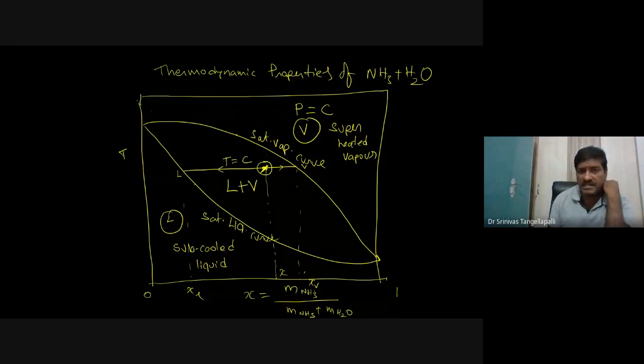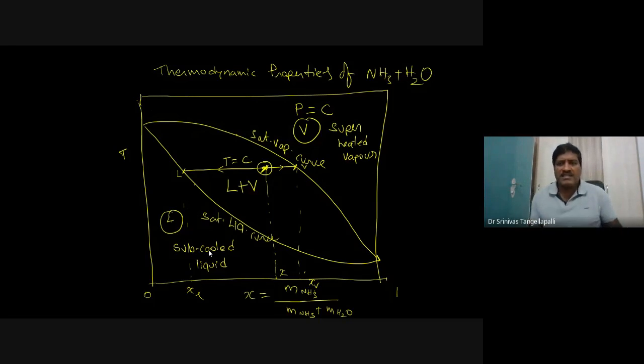One is the concentration directly at that state, that is the strong solution concentration, and this mixture also has the concentration at the saturated liquid part, and also the concentration at the saturated vapor part. You may ask how to solve these points, the liquid state and the vapor state. This can be solved using the enthalpy chart. Similar to the temperature chart, enthalpy charts are also available. In the enthalpy charts, it's easy to evaluate the mixture using the lever rule, because enthalpy charts consist of one more extra curve which is called the auxiliary curve. That auxiliary curve supports the saturated liquid and saturated vapor, so that we can solve the mixture properties using a graphical solution.